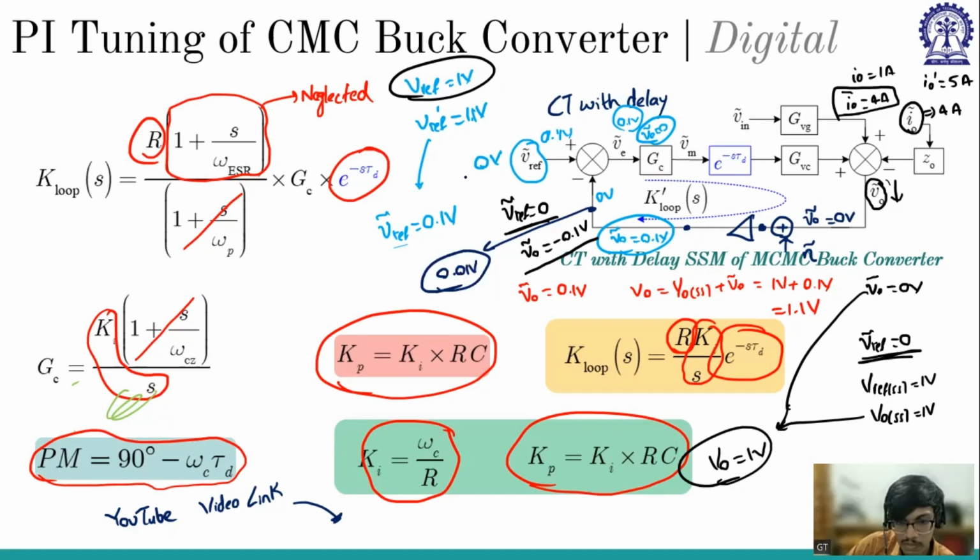Now V reference perturb is 0 volt and this is 0.01. The controller is negative, so accordingly it will change the control voltage so that this noise is nullified and I will get 0 volt here again. So the controller will take care. Whenever the controller sees there is an error voltage perturbation, it will start acting and nullify that effect so that it reaches the steady state.